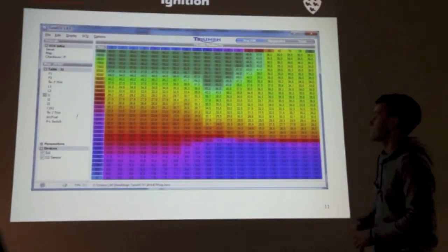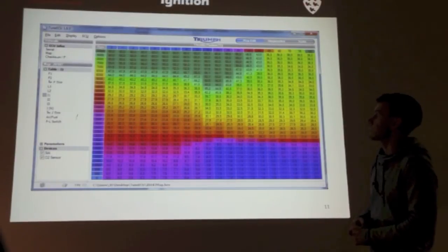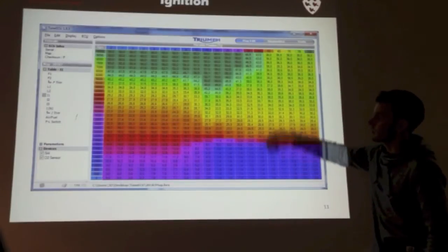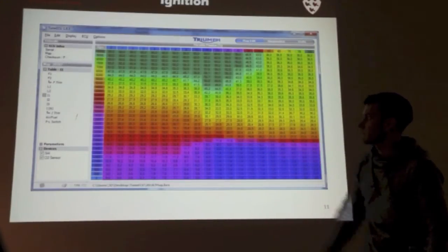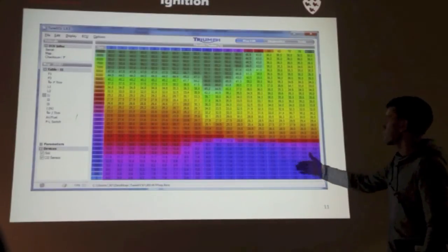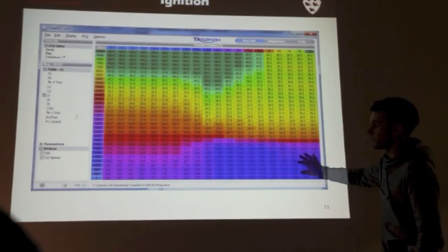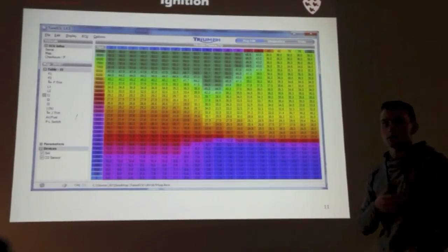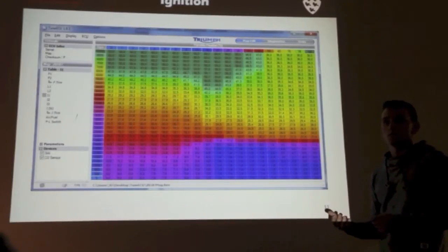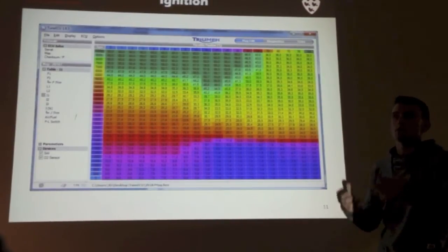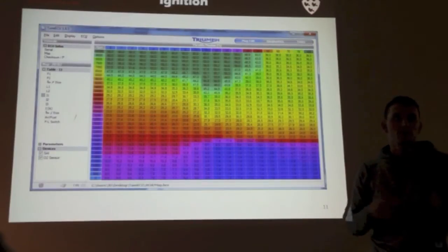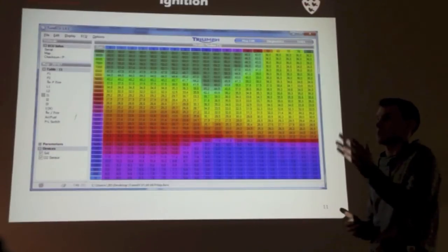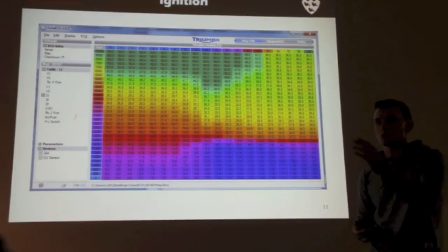And then here you see an example of a timing table. Again, the axes are a bit mixed up. Throttle position on the top there. RPM is increasing vertically there. So you see at low RPM, even high load, there's hardly any advance here. High load conditions often mean that your engine's running quite hot. If you have more temperature, your burn rate increases, thus you need less timing to achieve the same point of maximum cylinder pressure after top dead center.